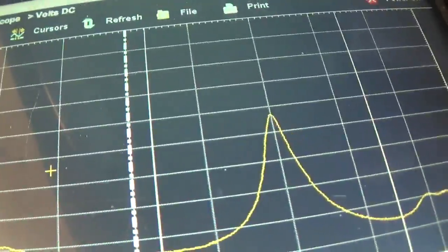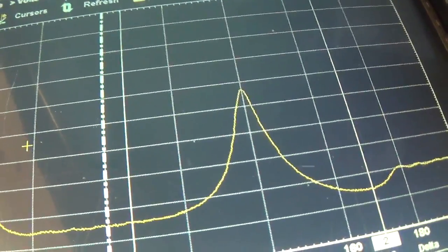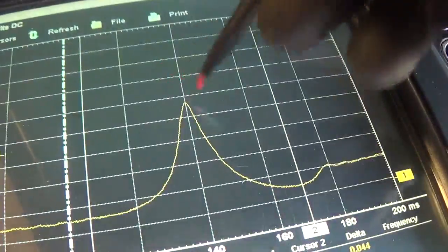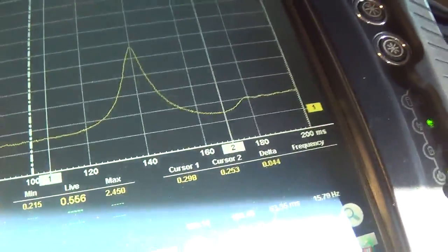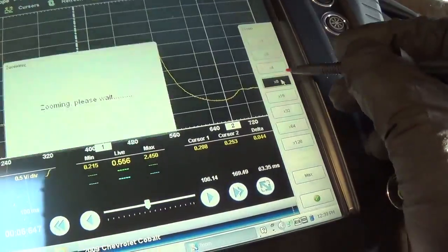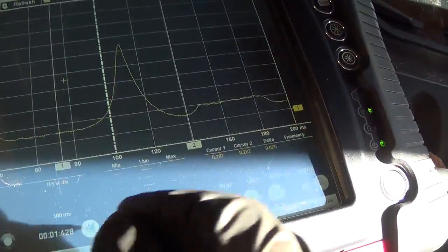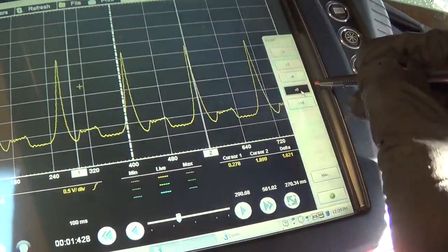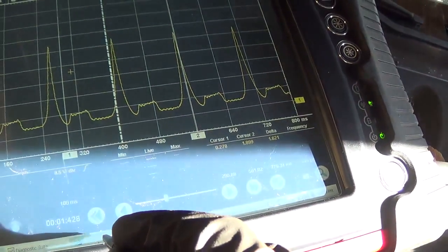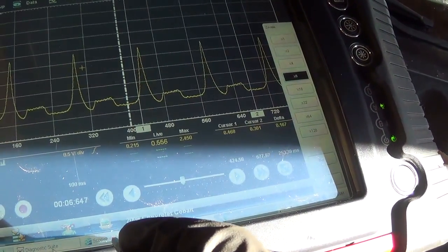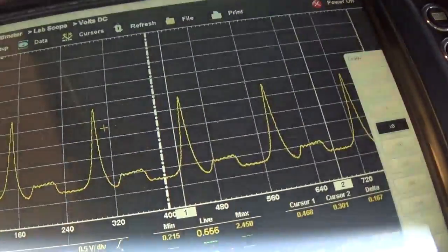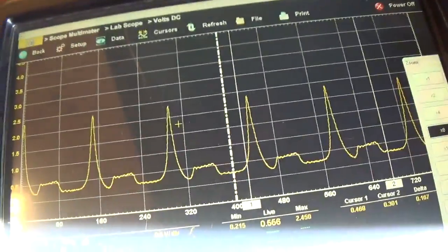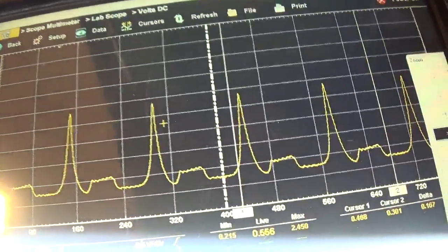So obviously the cylinder is losing some mixture, some air on the compression stroke. Now if you look at these waveforms, zoom out, they don't look all that different, do they? Here versus here, I mean, not a big difference. Just eyeballing it. But if you look at the numbers, we can definitely say there is a difference.